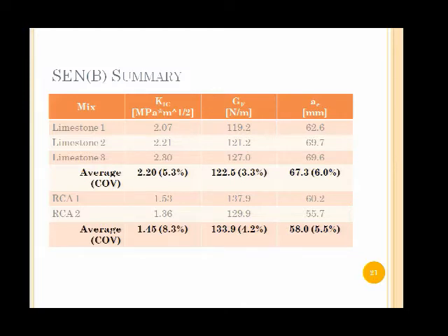And so these are roughly the same values, and one of the reasons we think probably these are similar is because this concrete is so old. It was cured, wet cured for about 200 days and then tested at 600 days. So if we tested this at 7 days, 14, 28 days, we would see a much larger difference between these values.